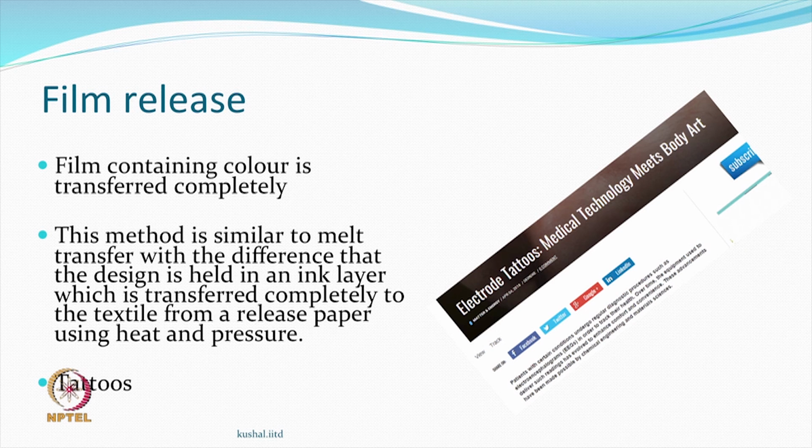It has become popular for different reasons today. The so-called temporary tattoos people want to use, it could be on yourself, and something similar could be on the fabric also. So, this itself is a market, but it is a transfer. The design is somewhere on the release film, and the whole of the film on the release paper gets transferred to whatever surface you give. For tattoos, obviously the whole system is designed so that you do not have to heat it, right. It is a room temperature transfer, you just have to apply a certain pressure and remove, and you are not looking at permanency there. If you are not looking at permanency, you wash it off, it goes, very good, next time, next design, and you are happy.